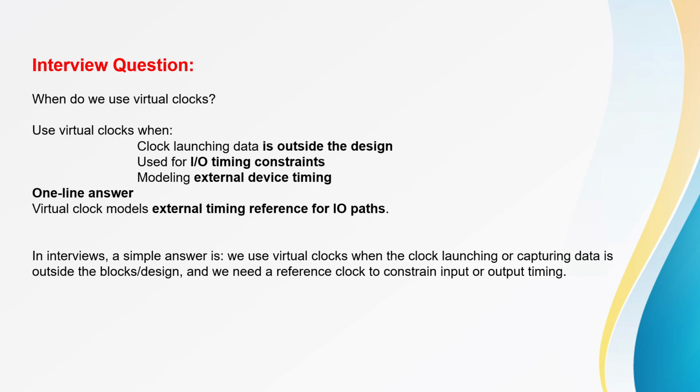So we can say simply that we use virtual clocks when the clock launching or capturing the data is outside the block or design, and we need a reference clock to constrain input and output timing.